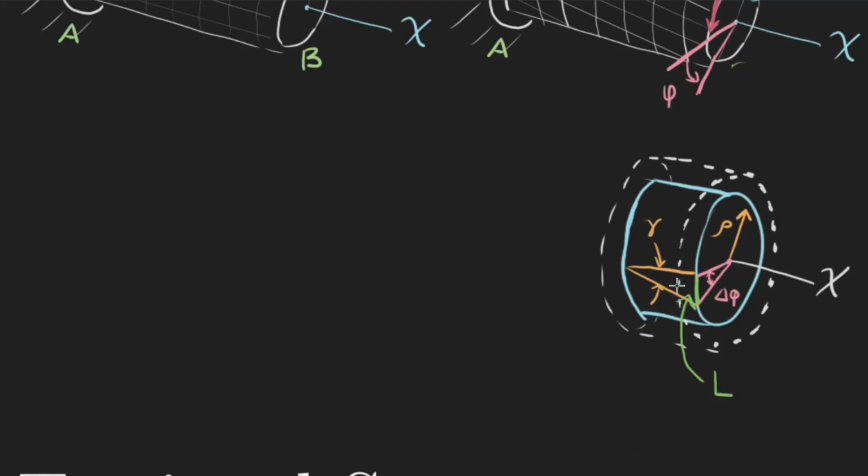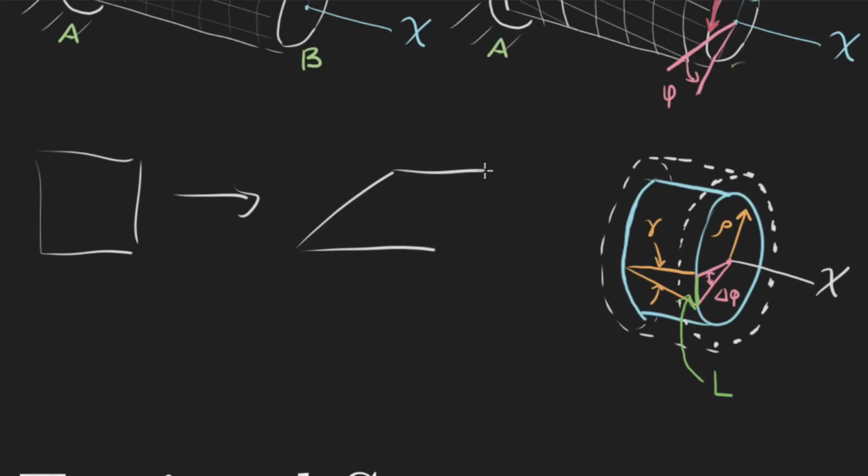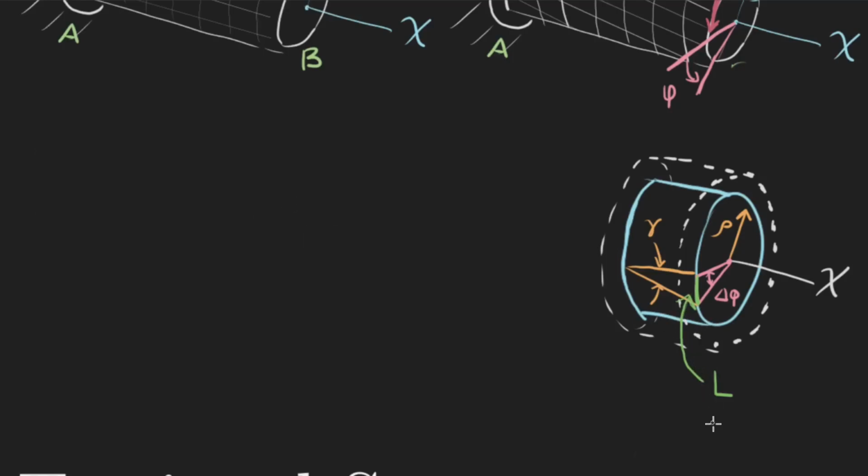And then this angle right here will tell us about our shear strain, because if you remember, if I have a rectangle right here and I shear it like this, the shear strain is going to be the amount that it deforms in this direction. So this delta divided by the length right here, we'll just call this L. I guess this would actually be our delta in this case. So if this is our corresponding delta, and this length right here would be our corresponding L, then our shear strain, gamma, would be equal to this length, delta, over our length, which is just delta x right here, right?